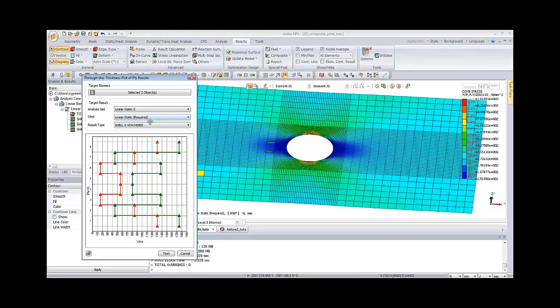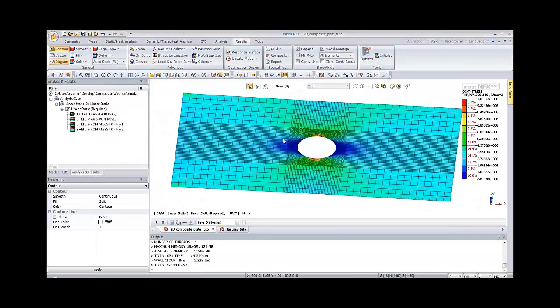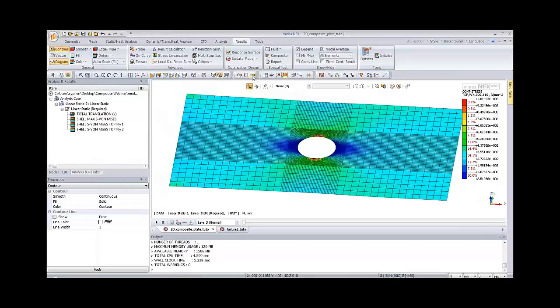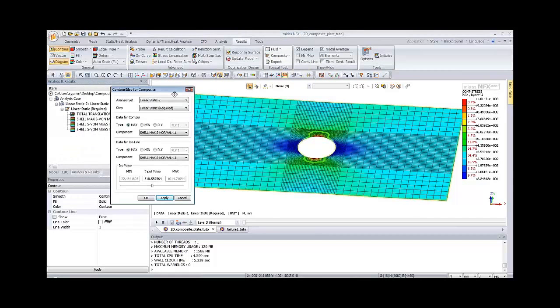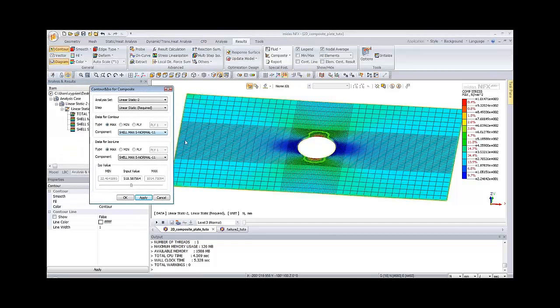And you have some complementary tools to check the contour and the isoline plots for composites. So using this tool you can check the data of the contour of one composite. So here it's a maximum for this normal 1-1, and the isoline, which corresponds to another criterion. So for example, you can check the von Mises isoline. So you can see the two on the same graph.